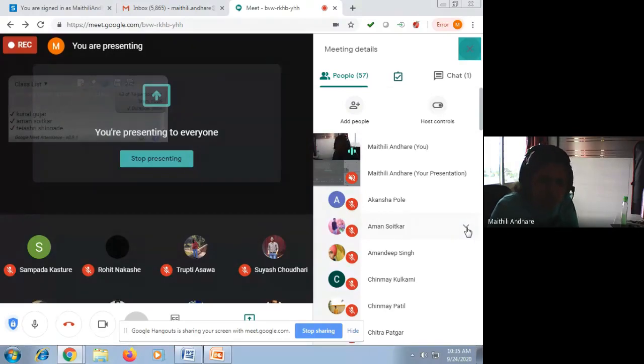First of all, load the TMOD register, then load the timer register. Then if any port you are requiring, just complement or pass the value to that port. Then start the timer, poll the timer overflow flag, and then stop the timer, clear the TF0 flag, and that's it. This is the basic flow for any timer programming, but according to the problem statement the user has to make some changes.